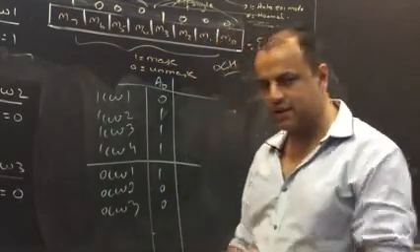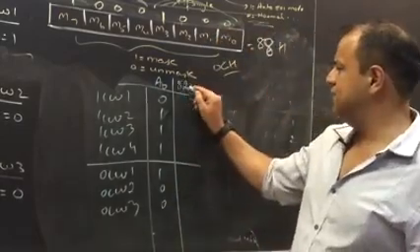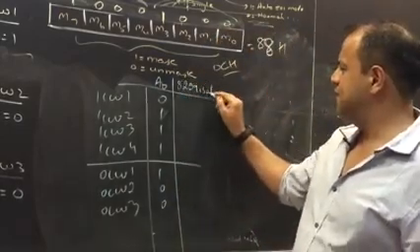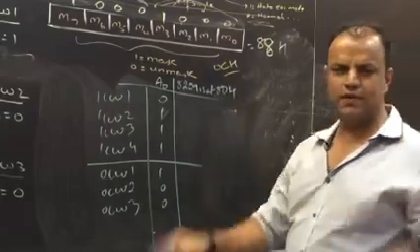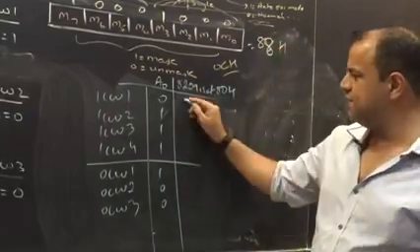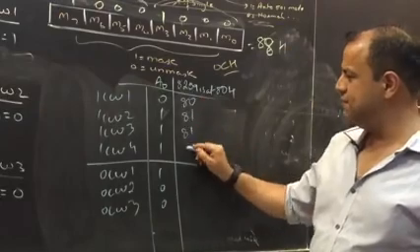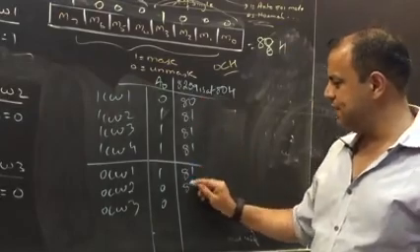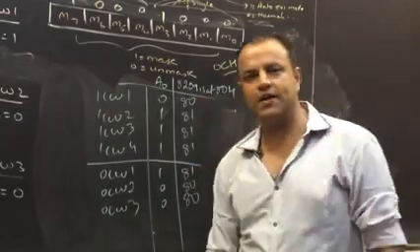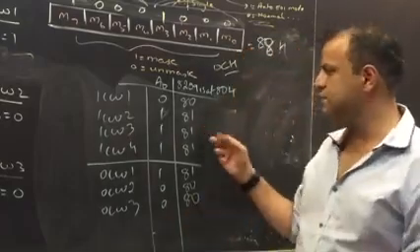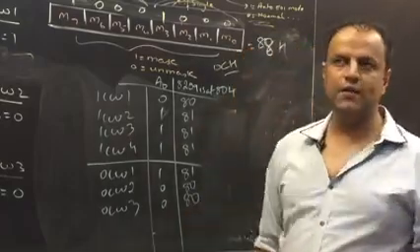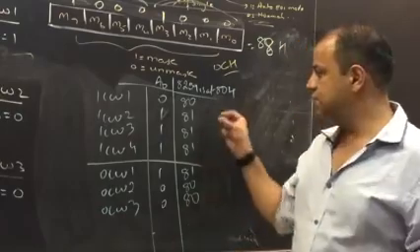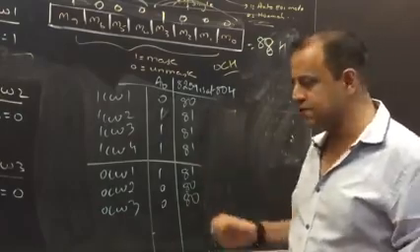Now what happens as the effect of this? If I tell you 8259 is at 80H, the commands will be given at 80, 81, 81, 81, 81, 80, 80. If I tell you 8259 is at 40H, then 40, 41, 41, 41, 41, 40, 40. If 8259 is at 62H, then 62, 63, 63, 63, 63, 62, 62.